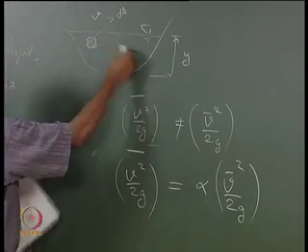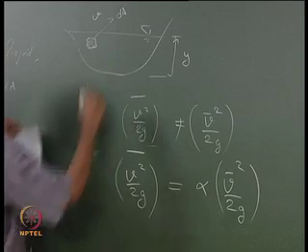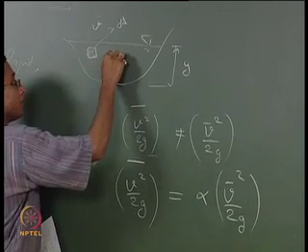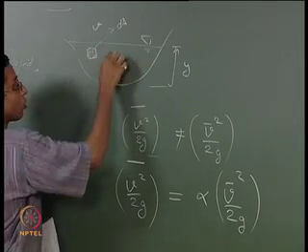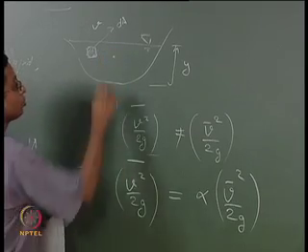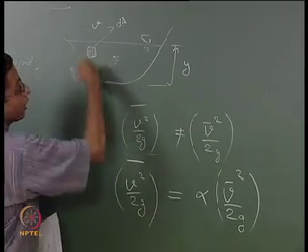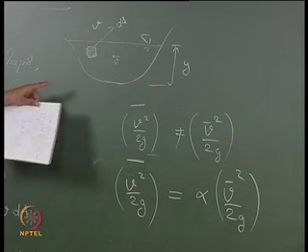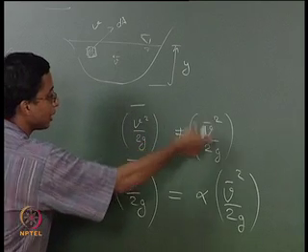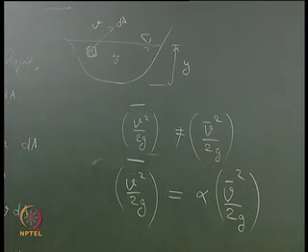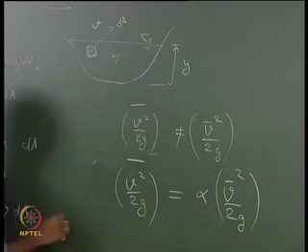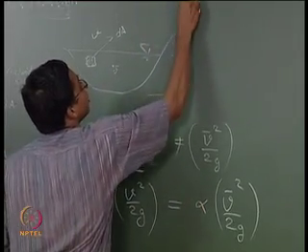If you add all of them and get the kinetic energy transfer, and if you first obtain a mean velocity for the entire cross sectional area and then try to obtain the kinetic energy transfer using that mean velocity, they will not be the same, because velocity appears in the third power here. So, they are not the same, and it is corrected using the energy correction factor called